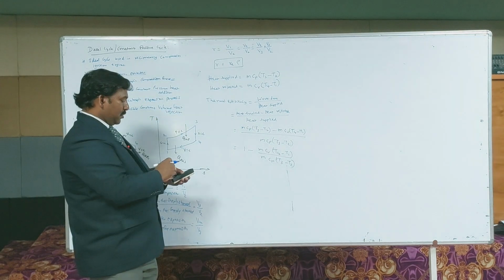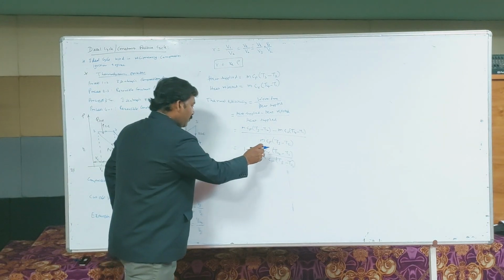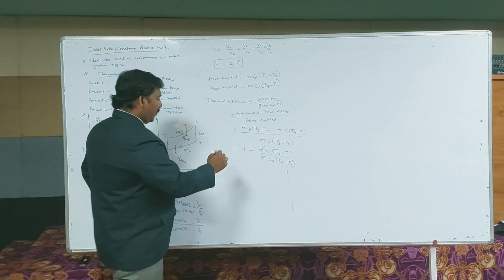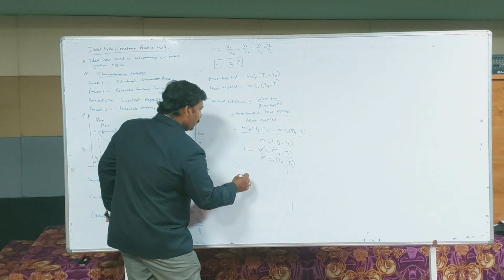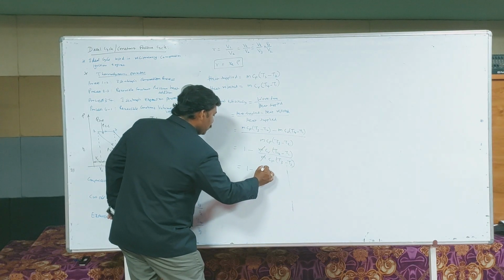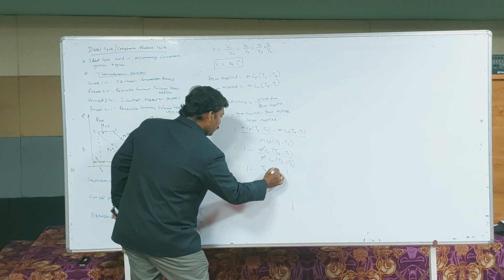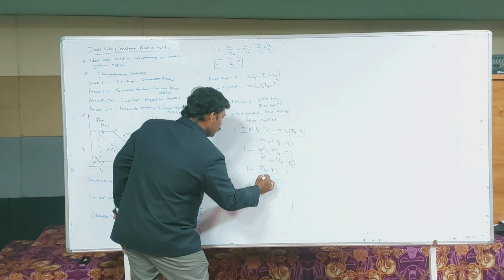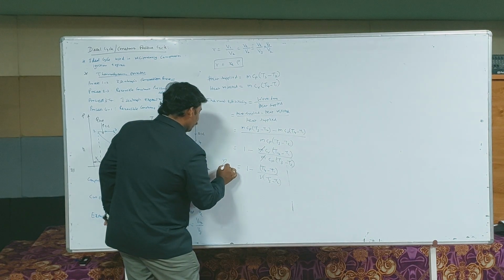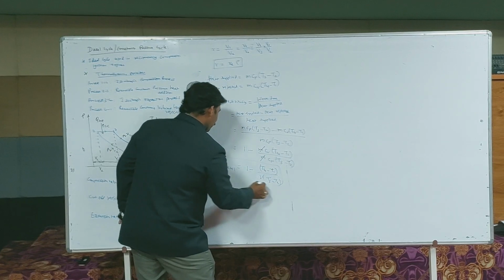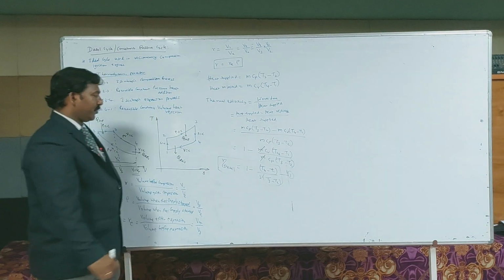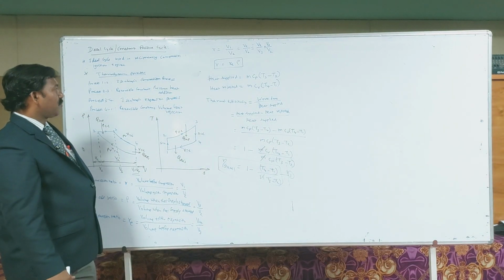In this expression the mass in numerator and denominator got cancelled and Cp by Cv is gamma. So, I can write 1 minus T4 minus T1 divided by gamma into T3 minus T2. We can denote this as equation 1.